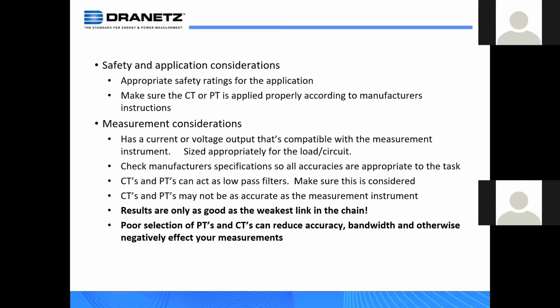So as an example, if I have a 13 kV application, it's not appropriate and it's not safe to take our flex CTs and put it around there. Or our clamps, even though they may be within the current range of the measuring of that transducer, they don't meet the safety requirements of that. So be very careful.